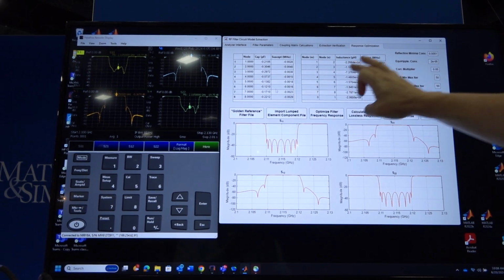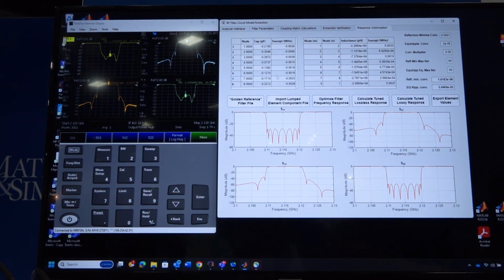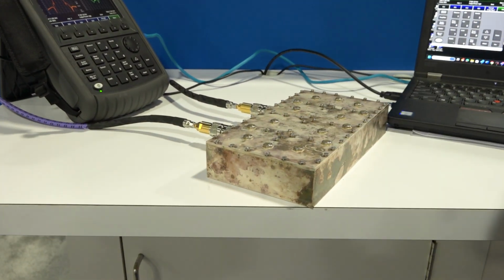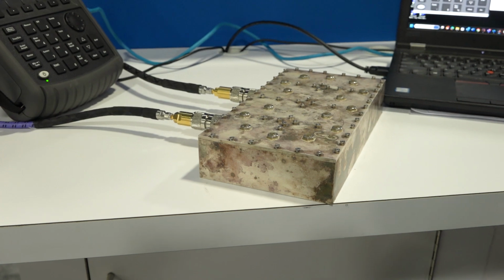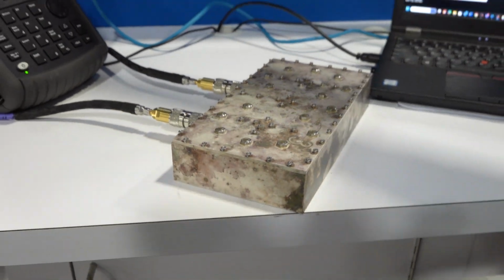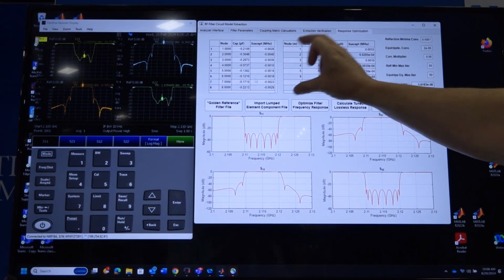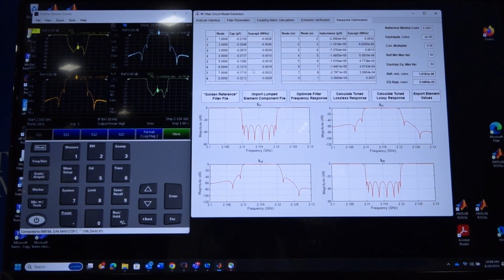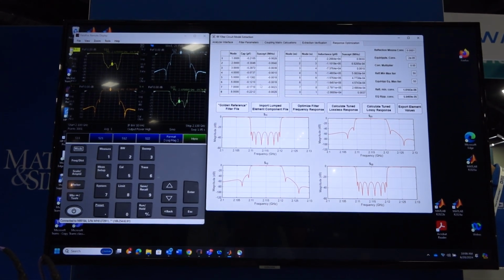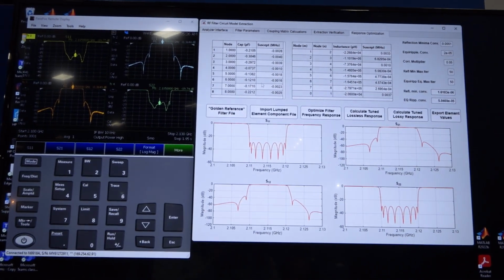These susceptance values need to be driven to zero, and this is achieved by making mechanical adjustments of these tuning screws, extracting a model, and subsequently achieving element values that lead to these susceptance values going to zero, and that will then allow for an extracted model that corresponds with the extracted golden reference model.